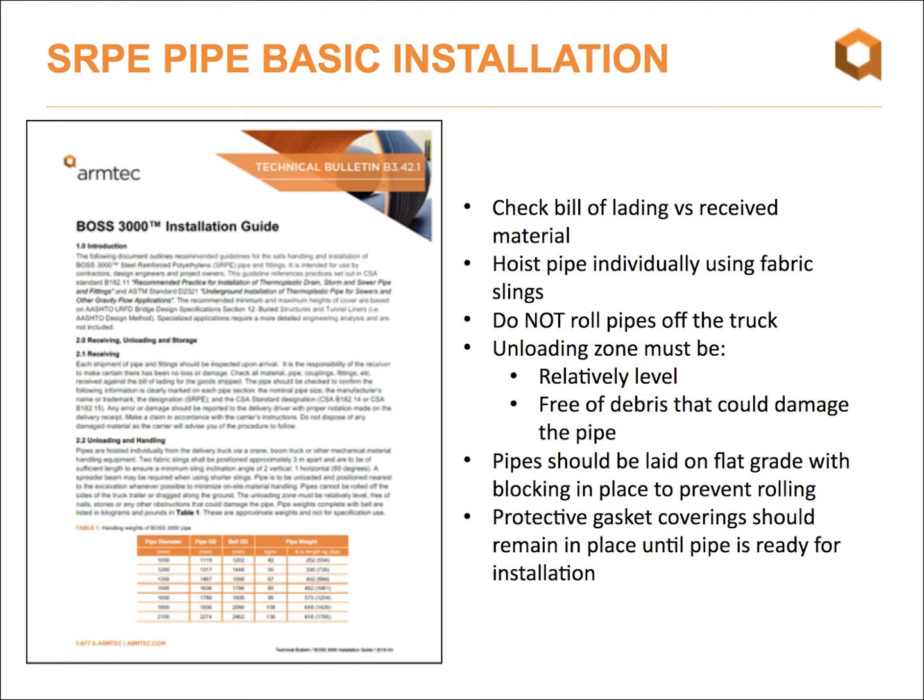And I mean, maybe I'm going to state some of the obvious, but after more than 25 years in the field, I've come to realize that sometimes the obvious needs to be restated. So you want to be sure that as the pipe reaches your job site, you're actually receiving what you have ordered. You want to be sure that you're not rolling pipes off the truck, please. You want to be making sure that you hoist the pipe individually using fabric slings.